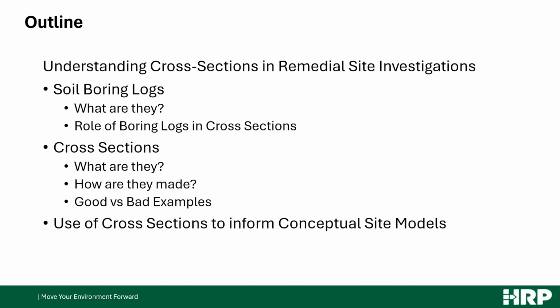Once you have individual boring logs, you then assemble them into combinations of how the lithology changes throughout the site based on different locations, and your boring locations are going to be based on what information you need to complete your conceptual site model. Once you have all of your soil borings, then we can move into using them to develop cross-sections, and the purpose of how we're going to use the cross-section to further the understanding of the site, contaminant transport, and any other factors that are important to the investigation. And we're going to end on some good and one bad example of cross-sections that have been used on sites that we've either made ourselves or are continuing the investigation after a previous consultant.